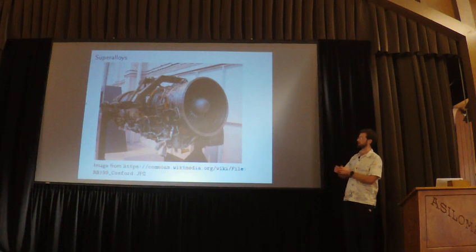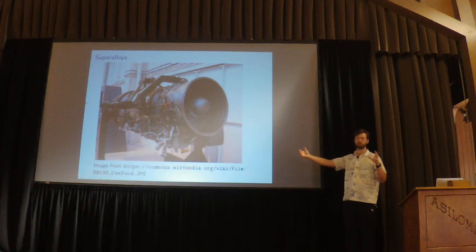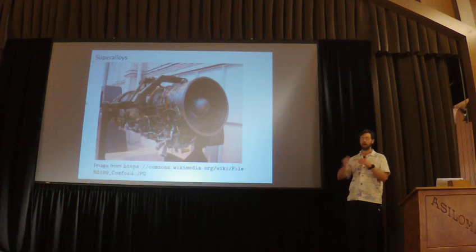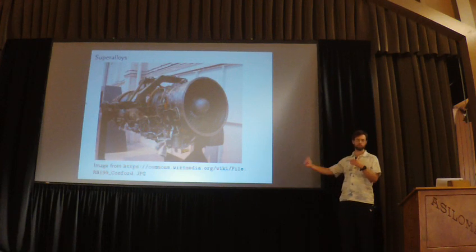Another application for superalloys is, I guess more generally, gas turbines. This is kind of the jet engine application. These are kind of small gas turbines. Big gas turbines are just used if you have too many liquid dinosaurs and you needed to burn them off for electricity or something. But kind of the game that people play with gas turbines is they want to operate them at higher temperatures. If you operate your turbine at a higher temperature, it's marginally more efficient. And even if these things get slightly more efficient, they burn a lot of fuel. And so if you can get them more efficient, you make a lot of money.